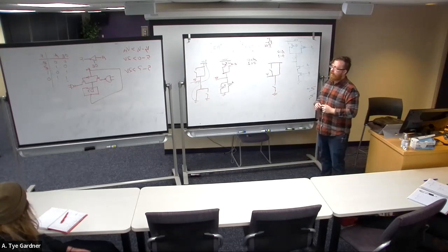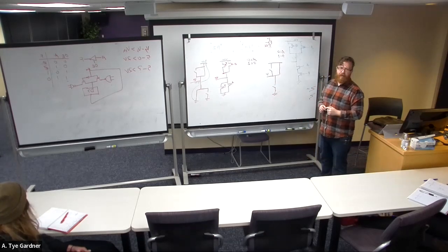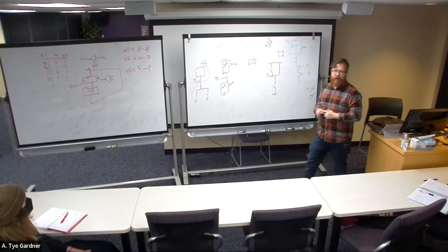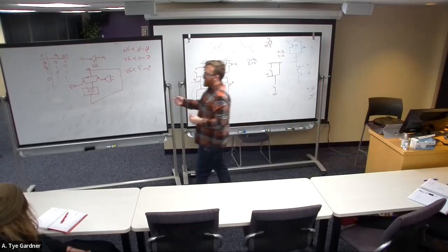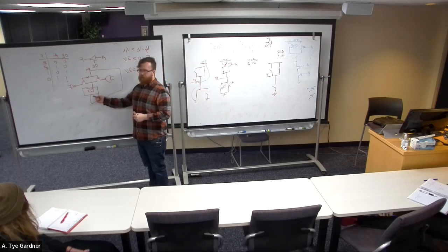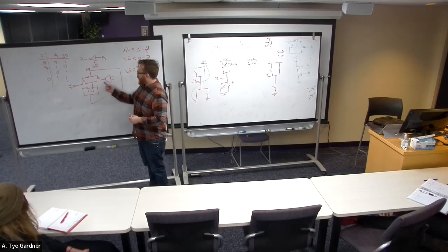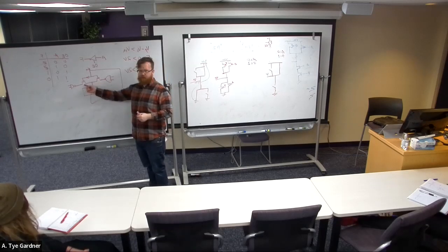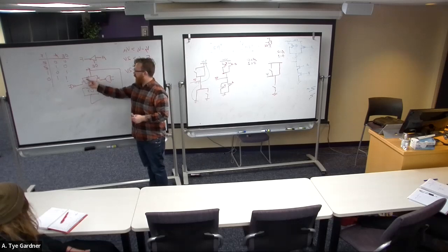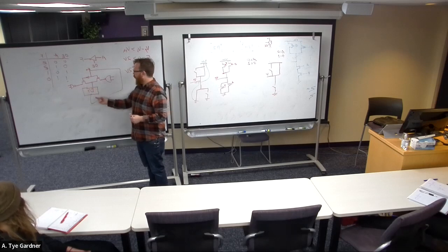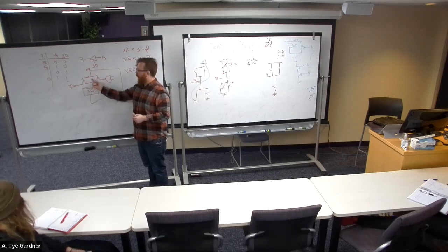Does that mean the inverter would flip so that it would turn the opposite NAND gate off? I mean, if I wanted to, I could turn it around, but I don't have to. But what happens, right, is right now, if it puts out a 0, it means I want to talk to this device, because a 0 gets inverted to a 1, turning on this guy. And 1 comes around, turns on this one, gets inverted to a 0, turns off that one.